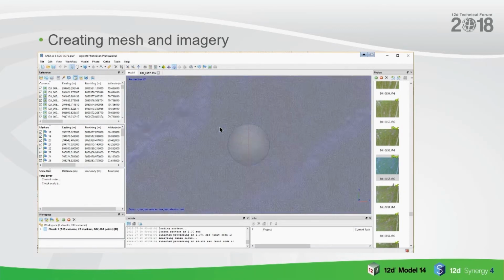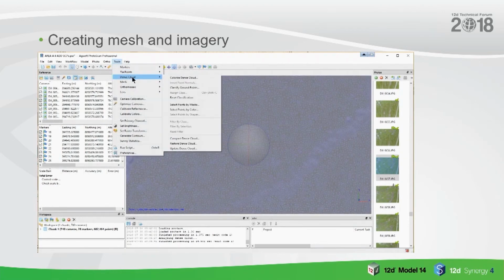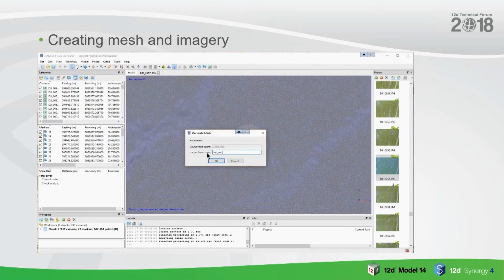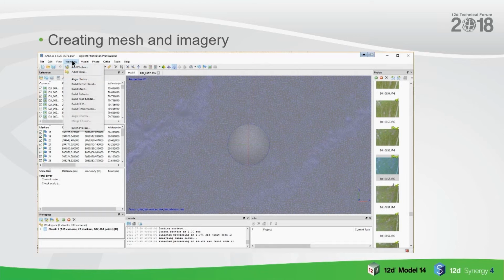We just did it from the ground ones. And you'll see that generally on a survey like that, you'll get about 60, 70, 80, 90 million points. So you probably want a slightly different version, the 5 million point version. When you get the triangles, there's a really great little option to decimate the mesh. If you've got 10 million triangles in there, it'll filter it out to however many you want.